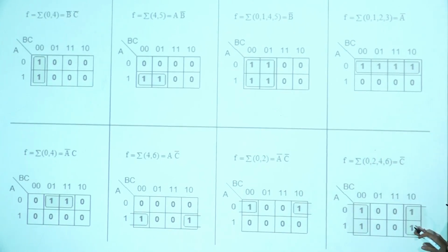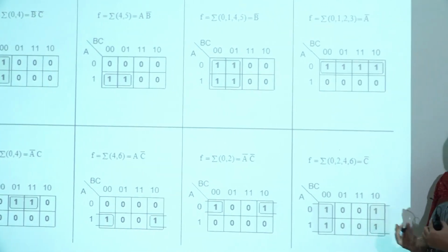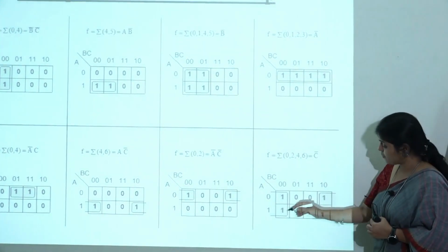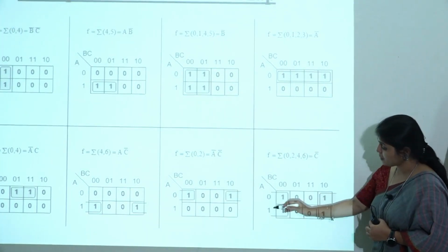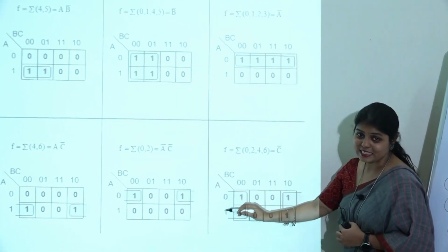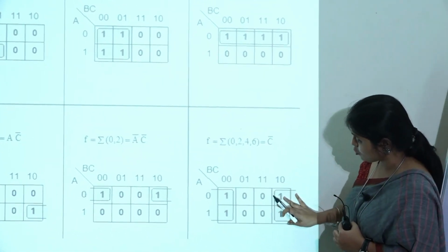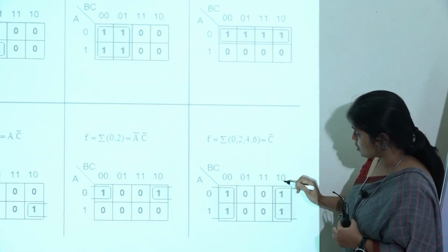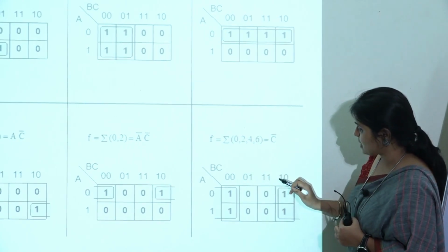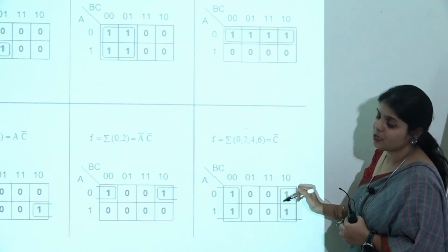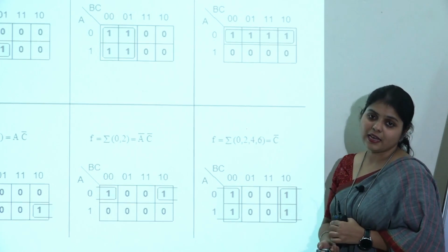Now, when you look into this, I have 4 variables on these 4 corners. So, I go for 4 grouping with this folding. So, what will happen here? 0 and 1 gets cancelled because this is covering these 2 rows, and when you look at these 2 terms, B and B bar gets cancelled, only C bar will be available. Hence, C bar is the answer.